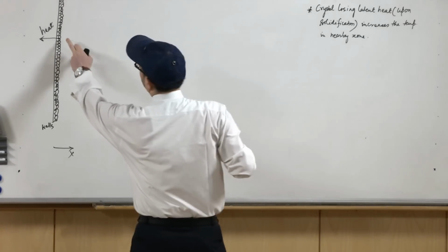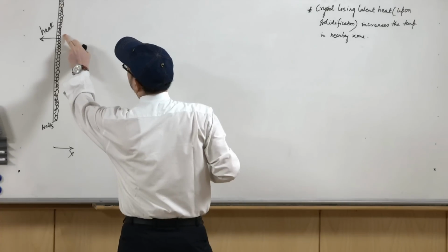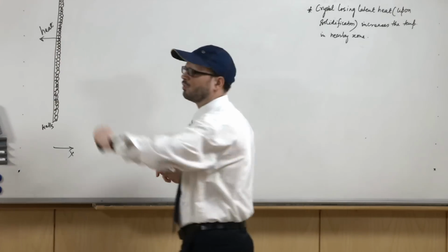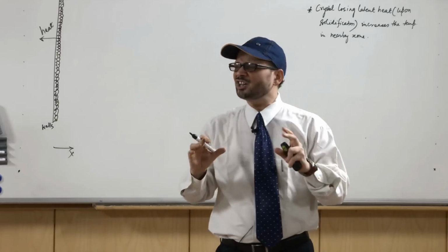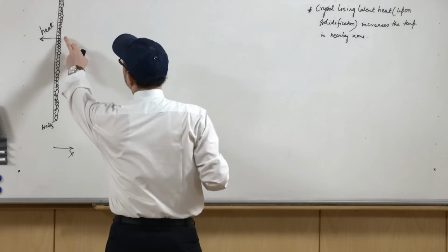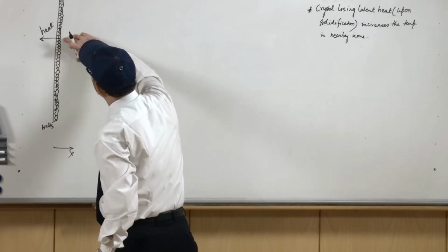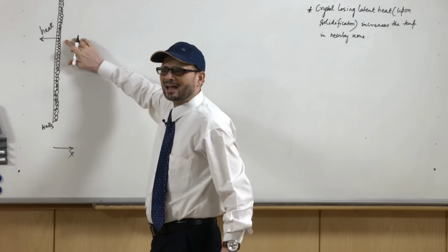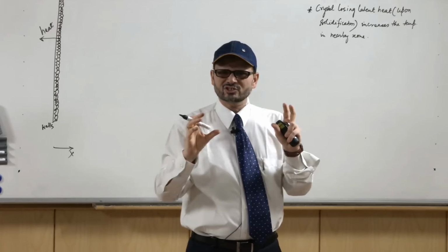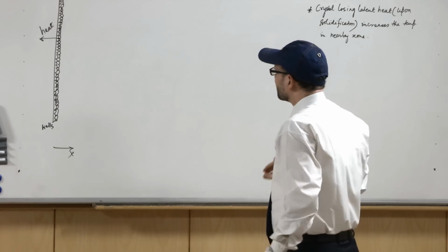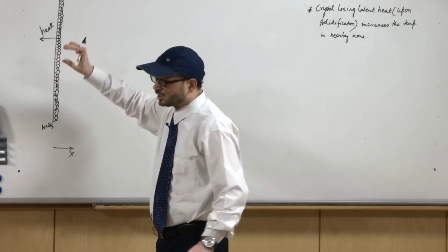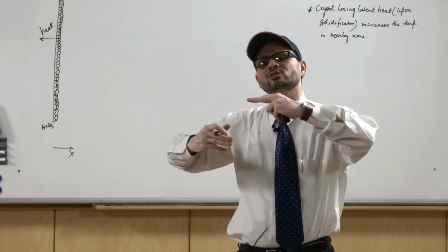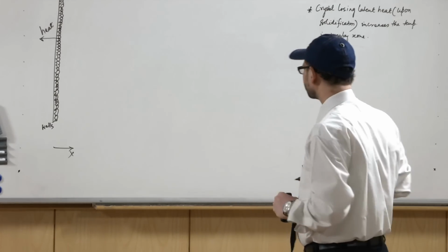The rate of nucleation, which was high because of large undercooling in the zone close to the wall, has decreased because of the increase in temperature in the region just near this solid shell formed, and because of that the nucleation ceases. And because of the increased temperature in that zone, growth becomes predominant.